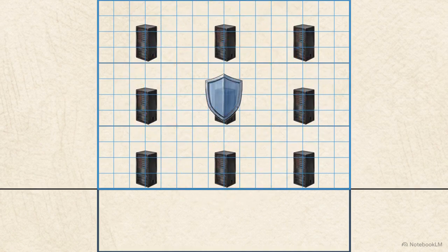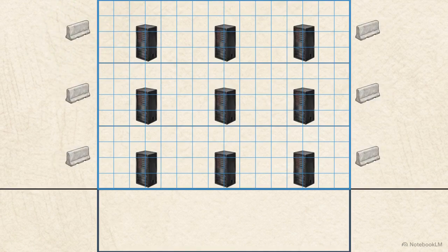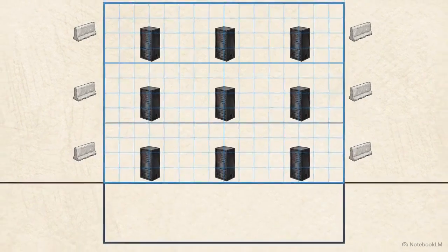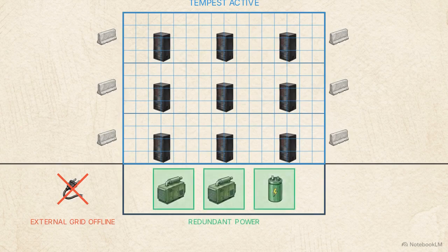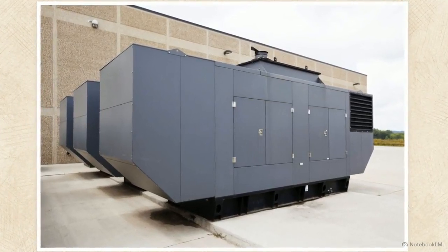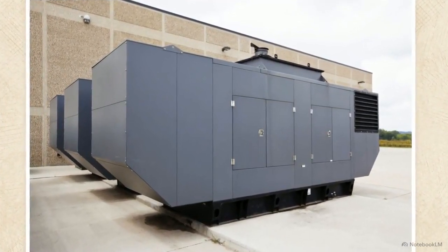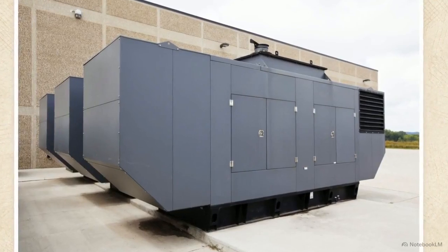These standards ensure that information-carrying signals are not intercepted through unintentional radio or electrical leaks. Tempest-certified structures are heavily shielded against internal signal leakage, highly resistant to EMPs, and blast-hardened against kinetic strikes. When external power systems drop during an assault, the facility relies on redundant infrastructure to maintain continuous network connectivity. This requires massive, uninterruptible power supply banks and industrial backup generators permanently standing by on site.